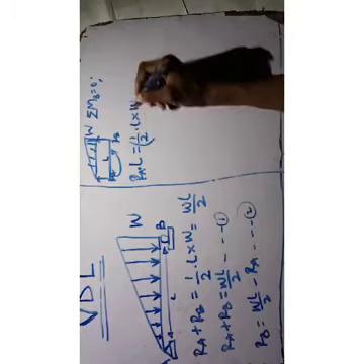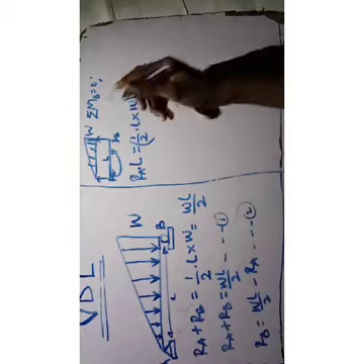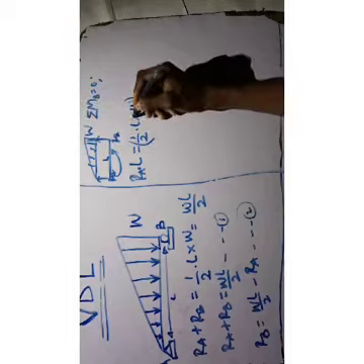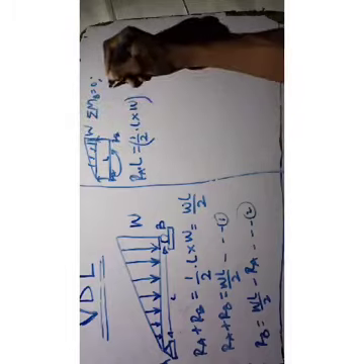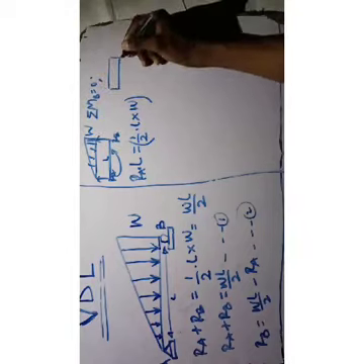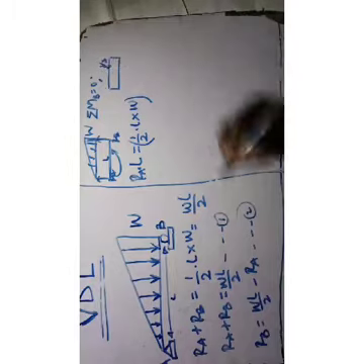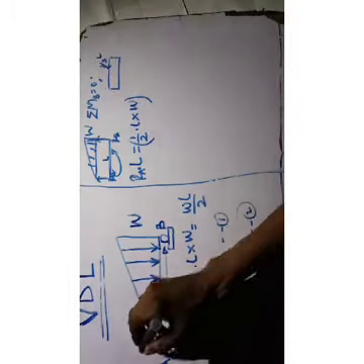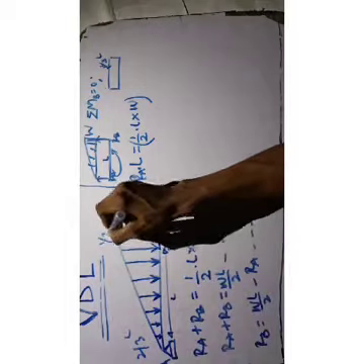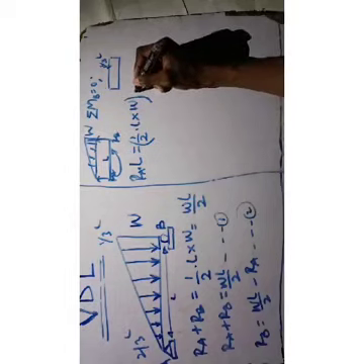This is the first part. Now, the next thing you do is multiply by the distance. It will change just like the UDL; the diagram will now change to be like this. But it will act at 1/3, because you are taking this as 1/3 and this as 2/3. The center of gravity will act at 1/3, and that will be 1/3 of L. This part is 2/3 of the length, and here is 1/3 of the length. So it acts at 1/3 of the length.